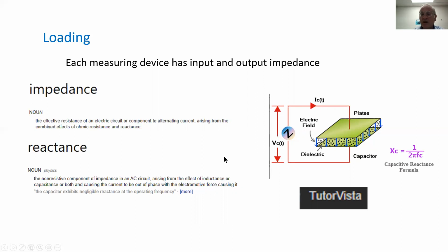For example, resistance does not depend on frequency, but the capacitor's resistance, the reactance, would depend on the frequency, and so does the inductor's. We see, for example, over here, that as the frequency tends to 0, this is an isolator. The resistance is infinite.